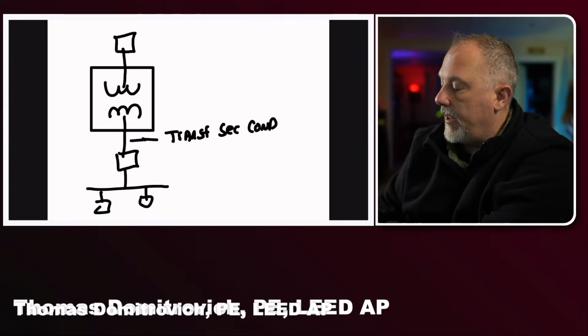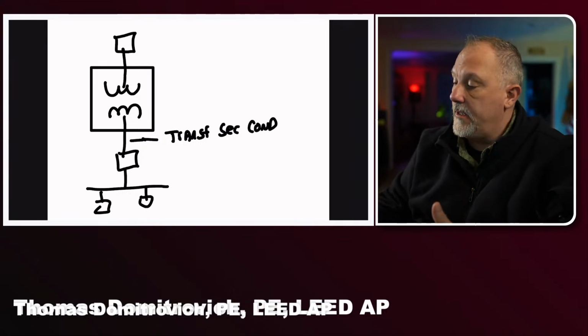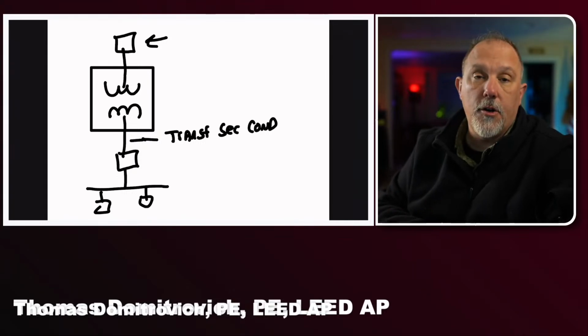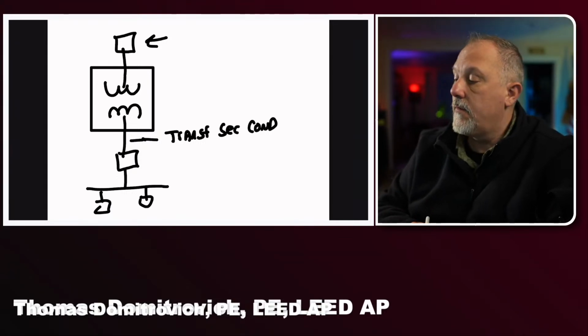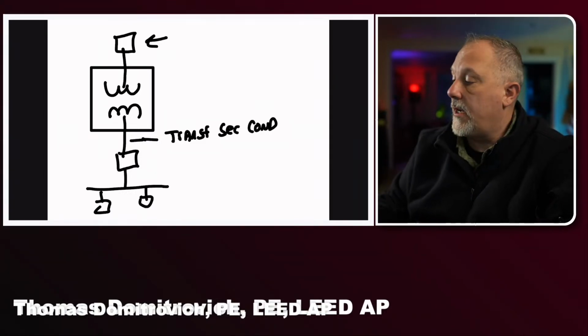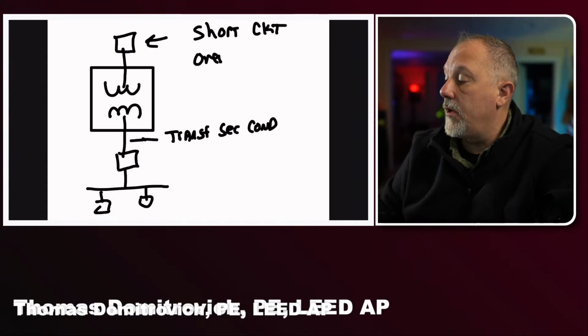And the question is, is that conductor protected from the primary overcurrent protective device? Now, what do I mean by protected? I'm talking short circuits, and I'm talking overload.